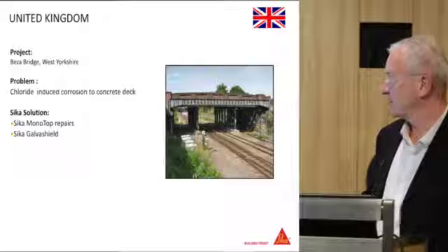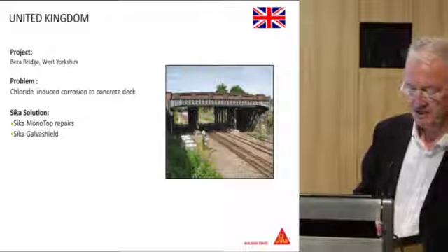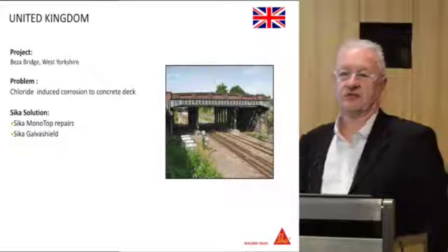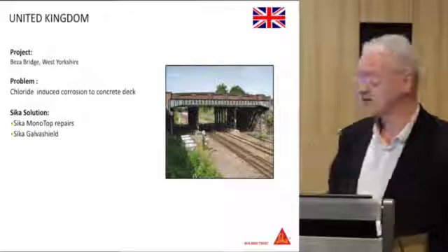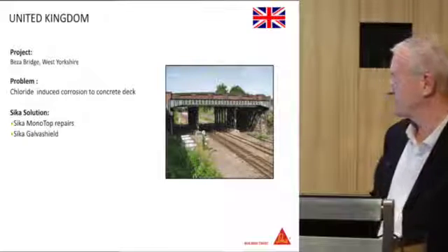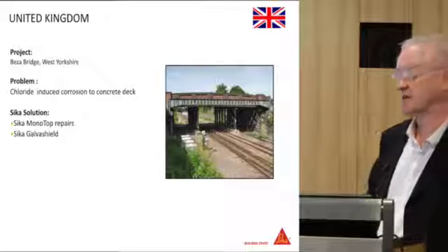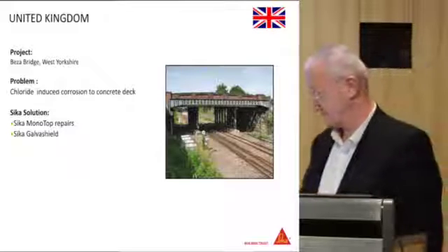And the last one, a bridge in West Yorkshire, very high chlorides, no option really other than to do the repairs and use Sika Galva Shield on there, which was the anodic anodes.